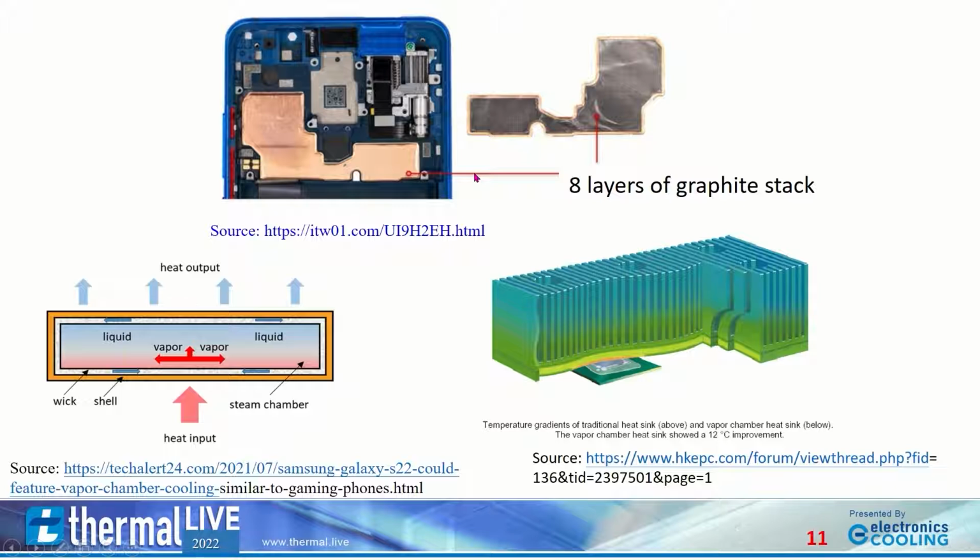Because the heat pipe, vapor chamber, or graphite or graphene sheet are used for thermal diffusion. In other words, the heat source area is different from the area of the condenser, and generally the heat source area is much smaller compared with the condenser area.